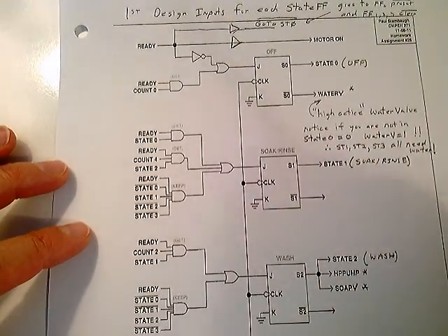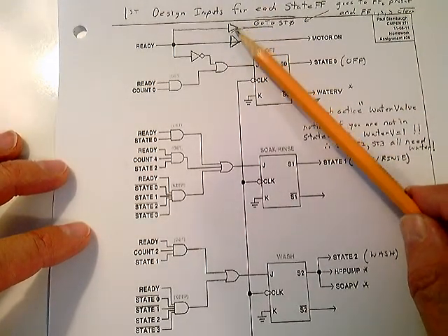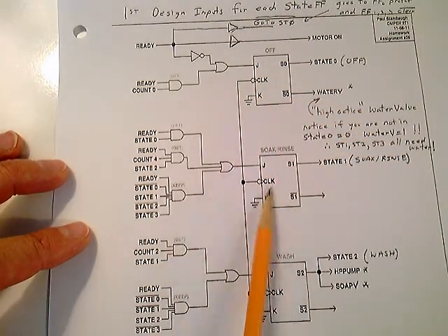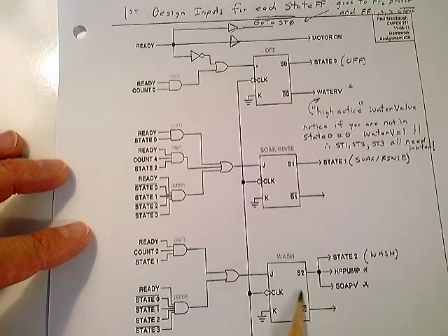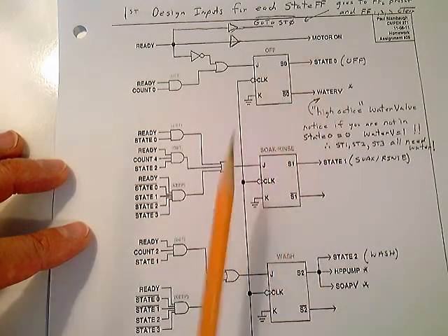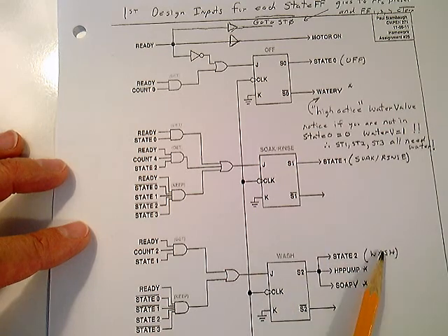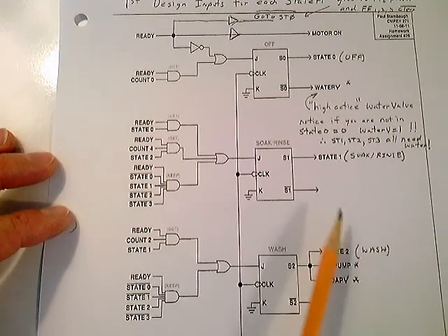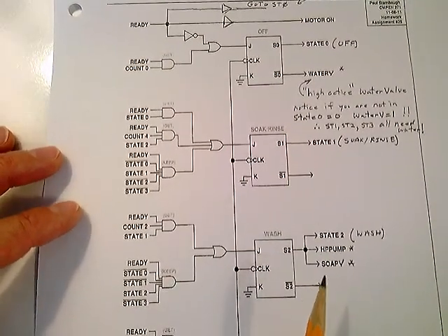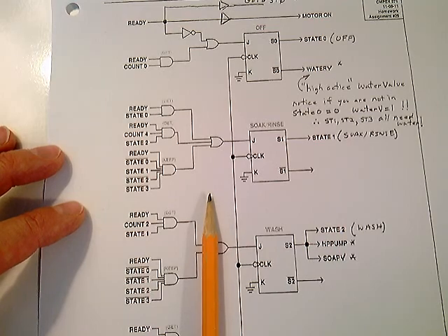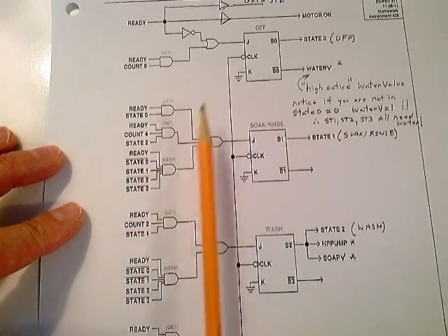This is what I was talking about up here on to stay in state 0. But there's your 4 flip-flops, 4 JK flip-flops. This would represent state 0 when you're off. This would represent state 1 when you're in either a soak-rinse cycle. This would be state 2 when you're in wash, and this would be in state 3 when you're in wax. This is very easy to explain to somebody. You know, it's a lot easier to understand, I think, than the synchronous logic design up to now, but it leads to more hardware, obviously.